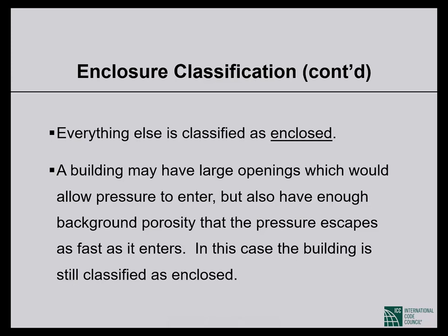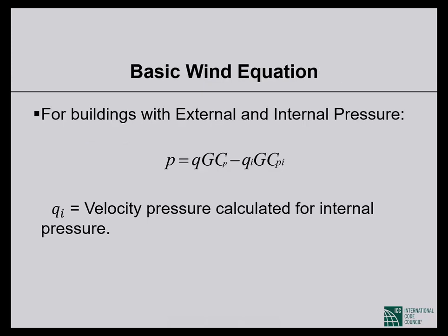So enclosed does not mean enclosed in the dictionary sense. By going by the dictionary, you would expect a jailhouse without openings on the faces. Enclosed building of ASCE 7 is not that. It simply means it is neither open nor partially enclosed by the definition of ASCE 7 or BNBC 2020.